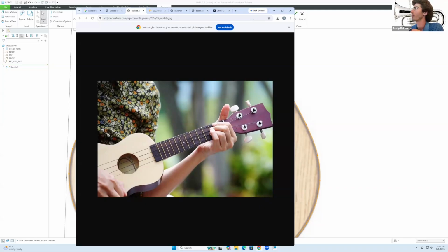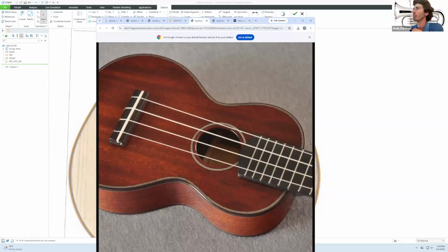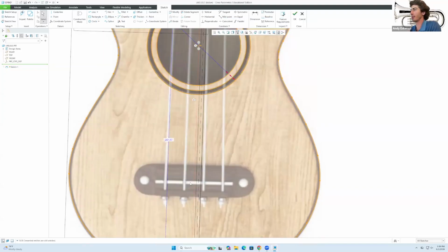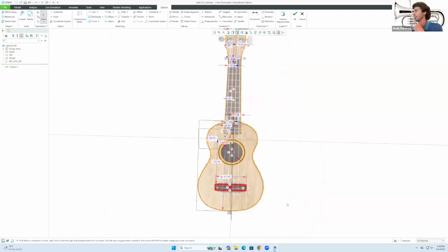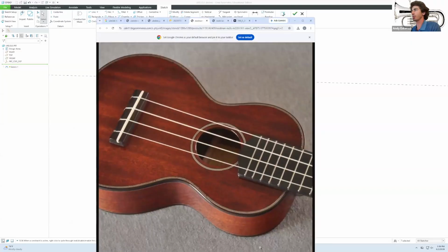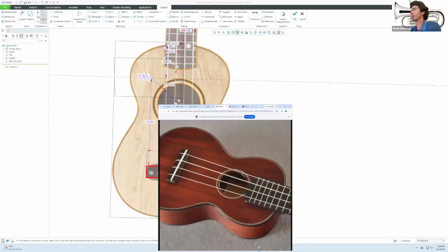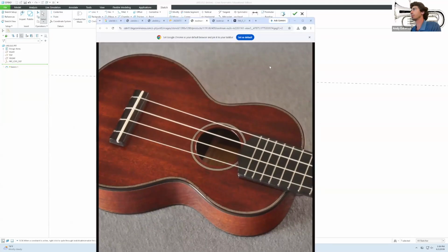In fact, I'm gonna also, did I taper? No, well, left it like that. But let me come back to this portion in here. So we're gonna make that a rectangle instead. So I'll come here, and I want things to be symmetrical more than anything. So the way to ensure symmetry is by using the center rectangle. So we can say you want that to be like that, as an example, right? That might actually be too big relative to, I think that's gonna be fine.